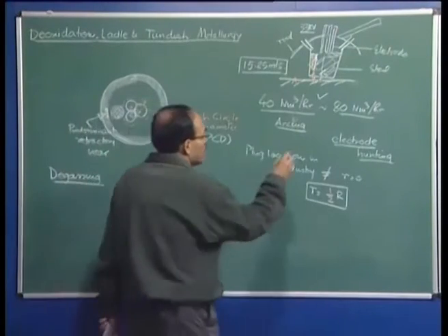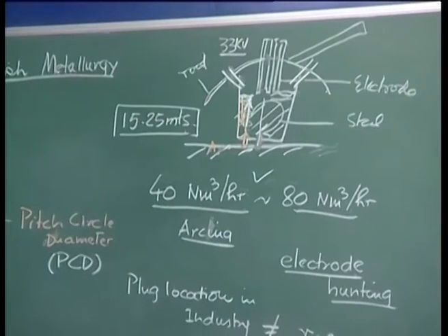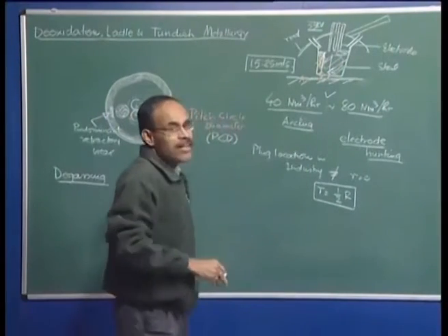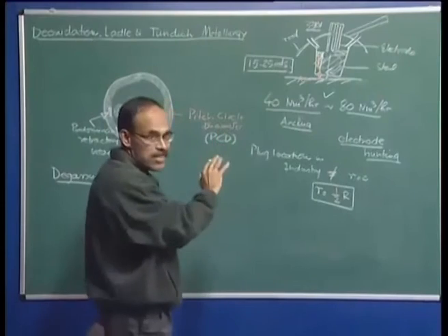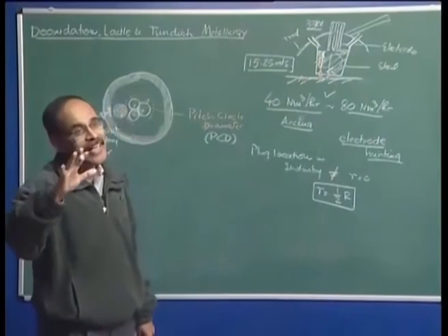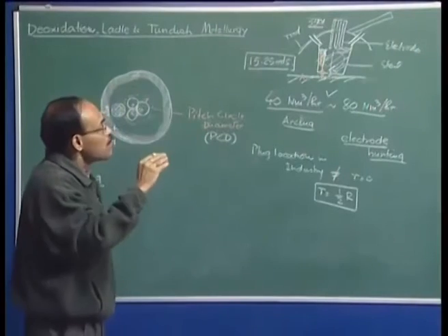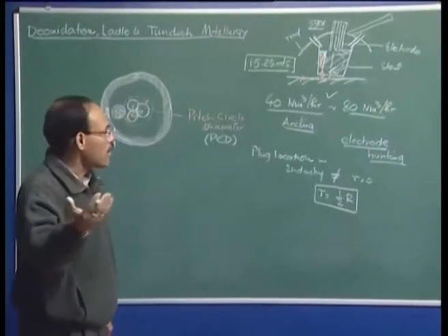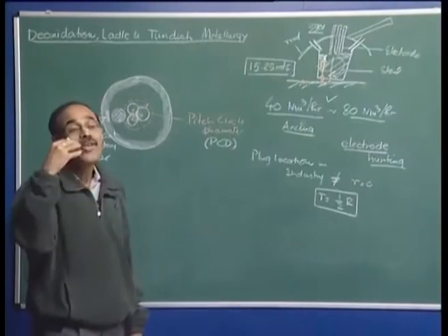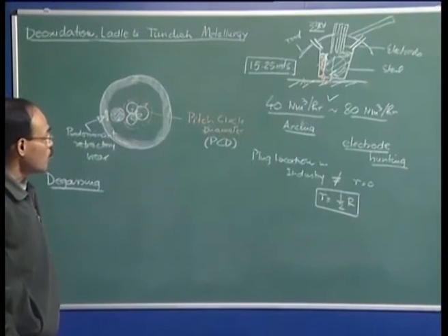So, carbon, silicon, manganese, sulfur, phosphorus and other alloying additions, niobium, titanium, etc. may be right, but at this particular stage the material may still contain some dissolved gases. And once we eliminate dissolved gases, that means the composition of the steel in the ladle is going to be perfect, its temperature is going to be nearly right, okay. And at the same time, towards the later part of ladle treatment, we only have to ensure the level of cleanliness in the melt, and once we have addressed that point, we can go forward and cast the steel through a steelmaking tundish ladle mold assembly.